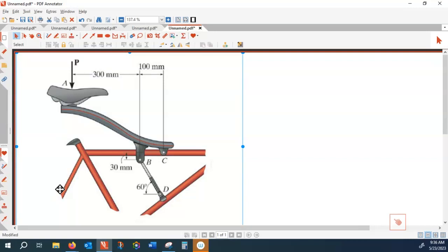What kind of member is it? Is BD a beam or a bar? Is it going to change the radius of curvature? Will it become shorter or longer? Something that can only shorten or lengthen is a bar. It's not a beam. A beam is when the radius of curvature changes. Just imagine if the gray one deforms, it is a beam because the radius of curvature changes.